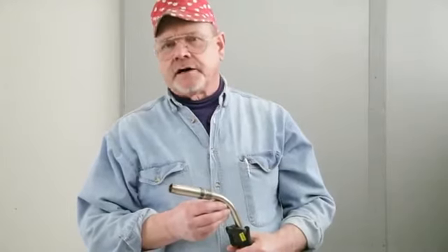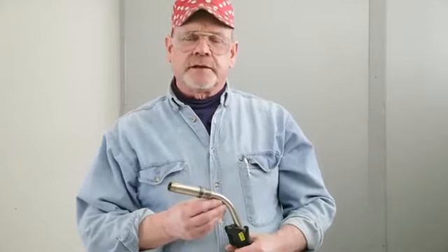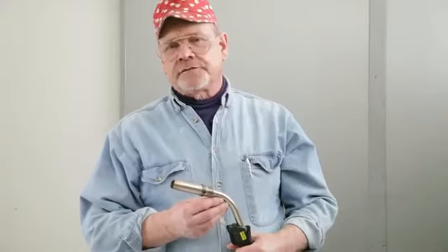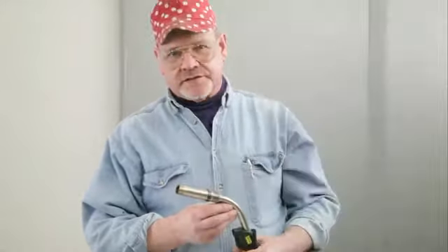For any of the MIG processes, an inert shielding gas is used. 100% argon may be used. Many prefer using argon-helium mixtures, with the helium percentage ranging from 15 to 25%. In this case, we'll be using a 75% argon, 25% helium gas mix.